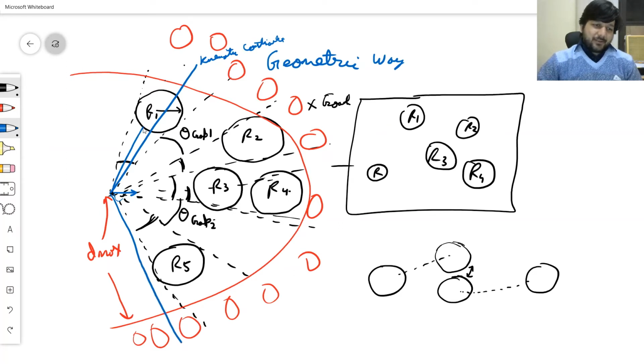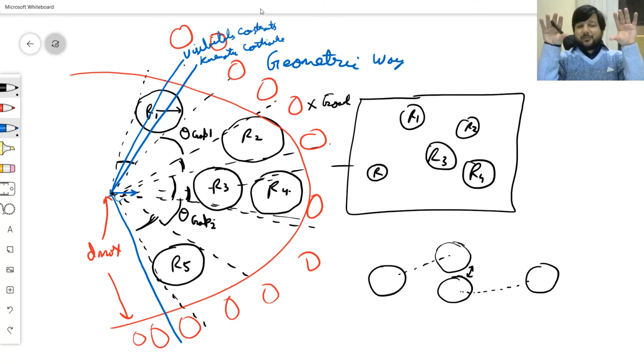And there are visibility constraints. So if you have a stereo camera which is looking at all these circular obstacles, the stereo camera will have a visibility range of, let's say, minus 50° to plus 50°. They cannot see beyond it, so you don't know what happens after it. Similarly, if you've got a series of ultrasonic sensors, they may only be fitted at, say, minus 90 to plus 90. You cannot see after that.